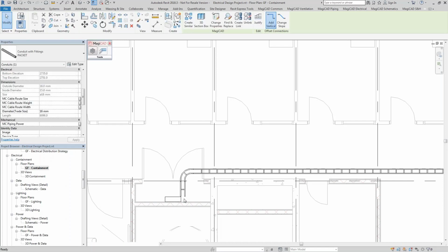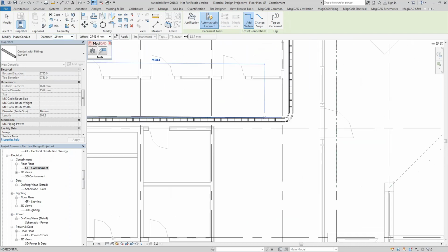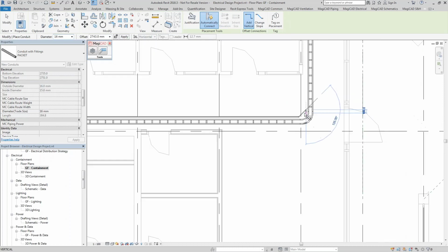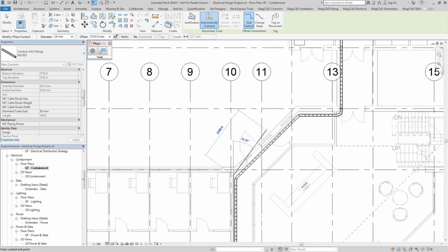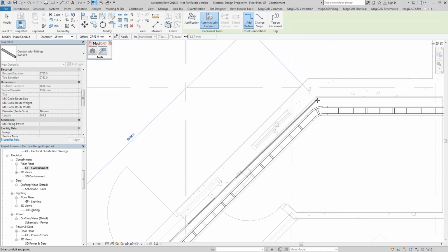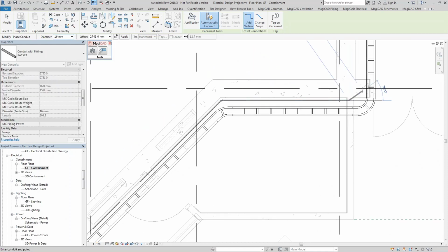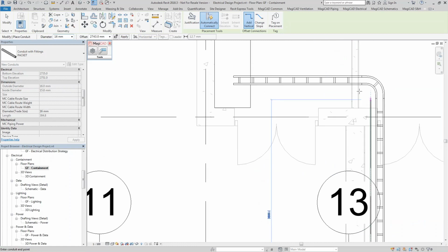And then once I click OK, I can then follow this through like so. I'm just being careful here to avoid clicking on the ladder itself, just because Revit loves to connect things together. So rather than have it accidentally connect this up to the cable tray, which will ruin the actual calculation process itself, I'm just going to detail this manually, and then it can obviously be moved afterwards over the containment as necessary.